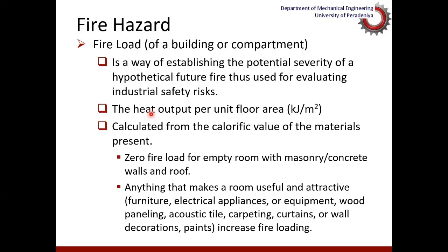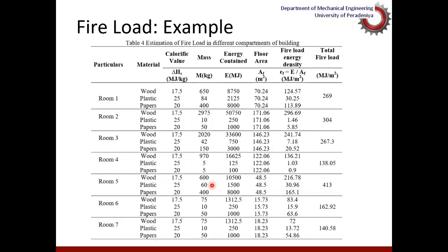So zero fire load is more or less, if you don't have anything which catches fire, it's zero fire load, and any additives could catch fire. So that adds the fire load. So these codes and other handbooks provide us the calorific value and the total fire load of different materials that you store. So depending upon different types of materials you store in a particular building, you could calculate the fire load. So that information is available in fire codes and